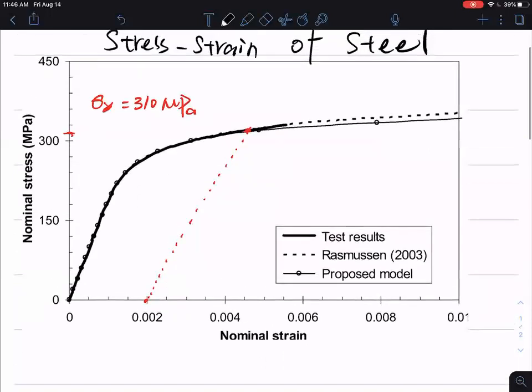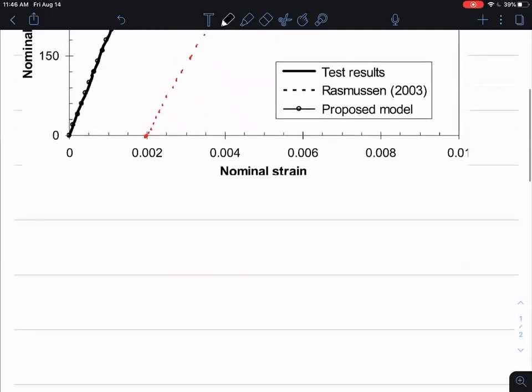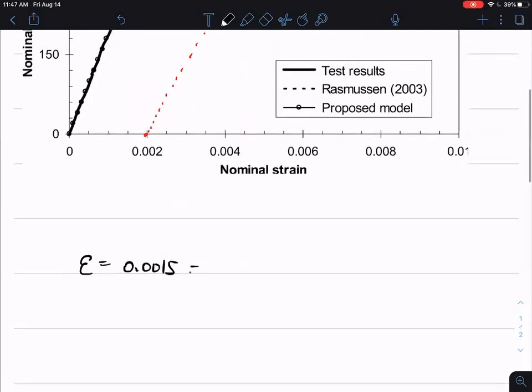So, we found the strain. We have the equation for the strain, that the strain equals the final length minus the original length, divided by the original length. Pretty straightforward calculation. Let me write it out quickly. We know the strain, which we read from the diagram, is 0.0015. From the definition, this strain equals the change of length delta L divided by the original length. The original length is 1 meter.